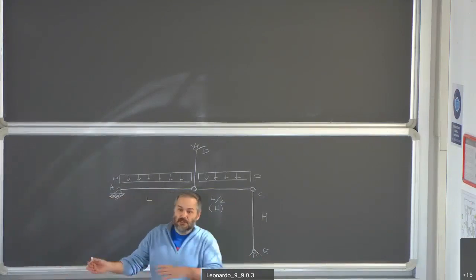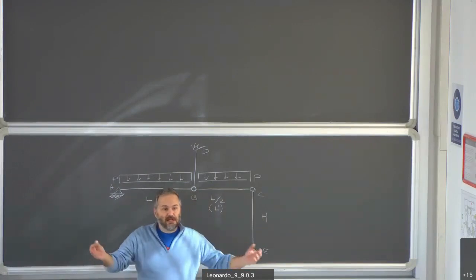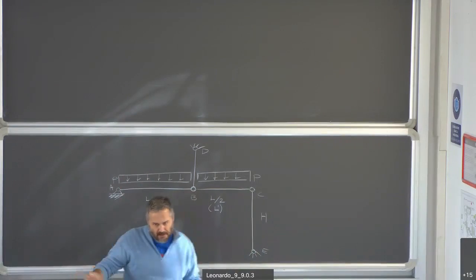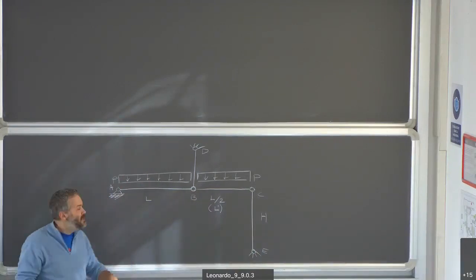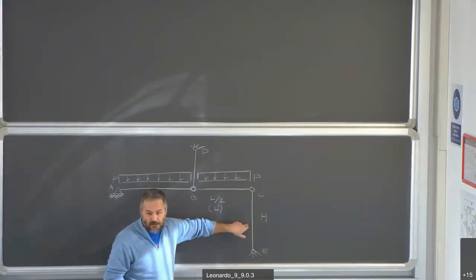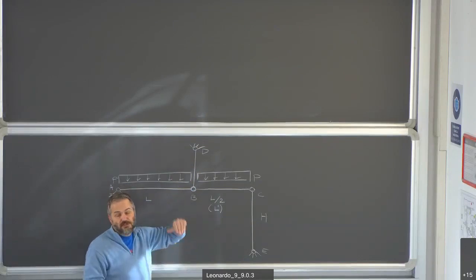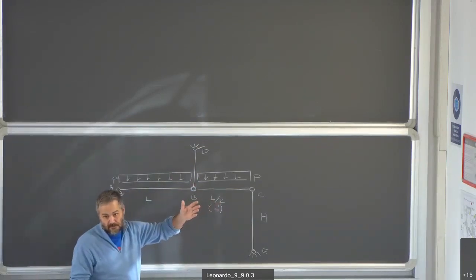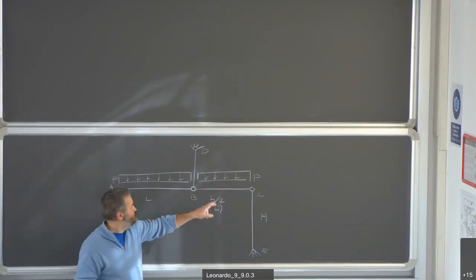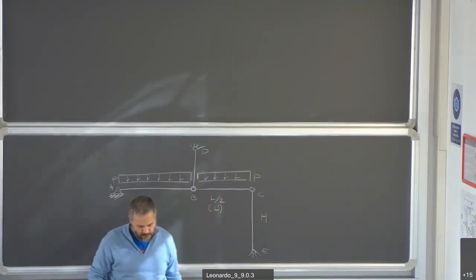For example, the whole load on one part with an intermediate support, which makes one beam deflect and the other one lift up, which basically pulls a member. Weird case. In this case, where there is a distributed load, you should expect this column to be in compression. And of course, this vertical member, which is above the horizontal members, is likely to be in tension. So this is the tie, this is the column, and these are the two beams. Got it?